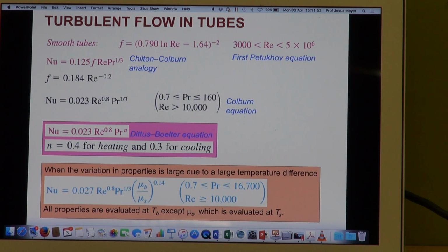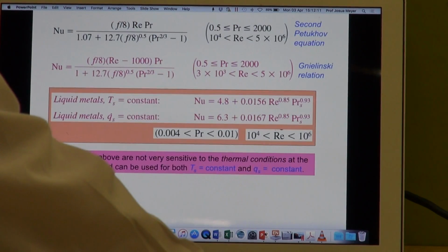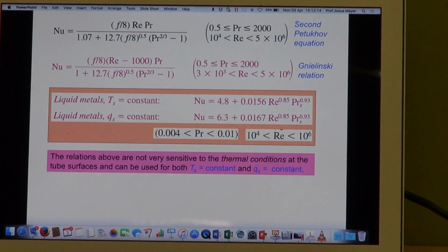Okay, so it depends on how much energy you have and how accurate you want to be in terms of calculation of getting the Nusselt number. But take note, all of them are a function of Reynolds number and Prandtl number, and some of them also a function then of the friction factor, taking into consideration the analogy between all these equations. Okay. Any questions on these equations? With the next lecture, we will do an example, or some more examples, so that it can be more clear to you. Thanks, Dan.